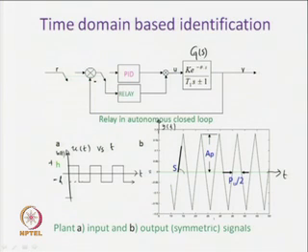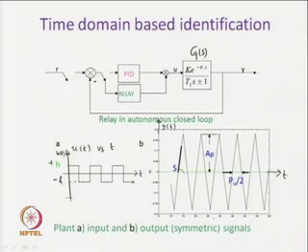So, we shall now make 3 measurements on the sustained oscillatory output, unlike the previous lectures where we used to take 2 measurements only, and those are the peak amplitude given by Ap, and the half period denoted by Pu by 2, where Pu stands for one period of the output of the system.